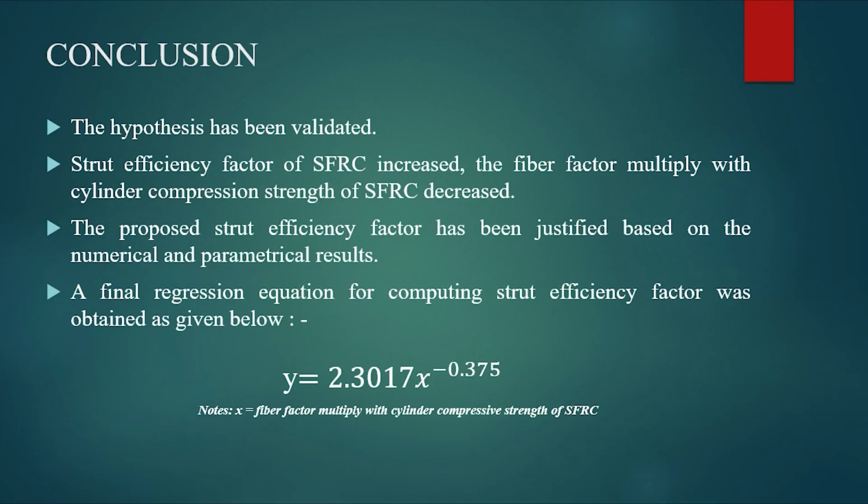So to conclude this presentation, the hypothesis has been validated, whereby the strut efficiency factor for SFRC is dependent on the fiber factor and cylinder compressive strength. As the strut efficiency factor for SFRC increases, the fiber factor multiplied with the cylinder compressive strength of SFRC decreases. Besides, the proposed strut efficiency factor has been justified based on the numerical and parametric results. Lastly, a final regression equation for computing the strut efficiency factor is obtained as given below.